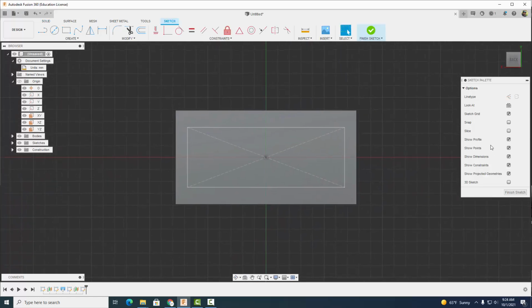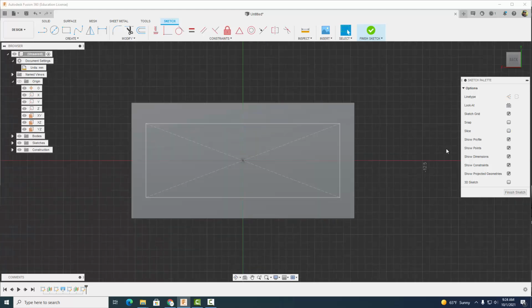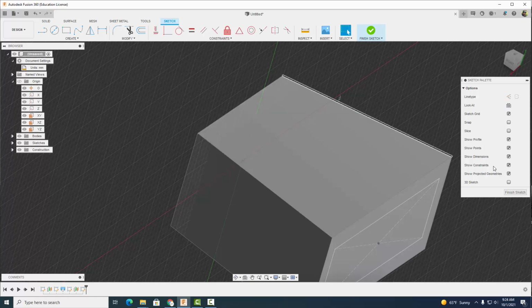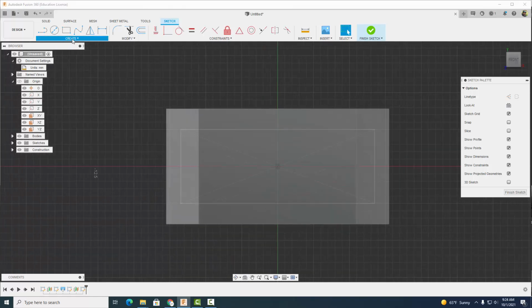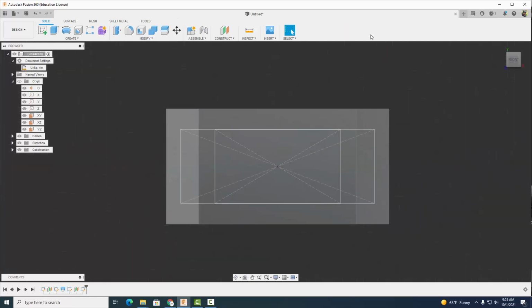Okay, and I'm going to go ahead and slice that open so we can see here. You know what? Maybe not. Anyways, let's go ahead now and draw out a second one. Okay, so you can see how our plane slices through here. So let's go ahead now and create a second center rectangle right here. And be careful, don't attach it to any hidden lines. We want these dimensions to be 5 by, hit the tab button, 8.73 millimeters. Hit enter. Okay, go ahead and finish your sketch.